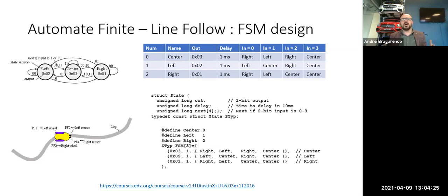Okay, depends. Depends how we are imagining. Drive to the left, to the right, or driving right motor. In this case, most probably we have here 1, 0, and that means 1, 0. In this case, we have to drive the left motor or drive the right motor, staying always 1 millisecond. Now, if we are in the center and both sensors are detecting, in this case, drive center continuously.